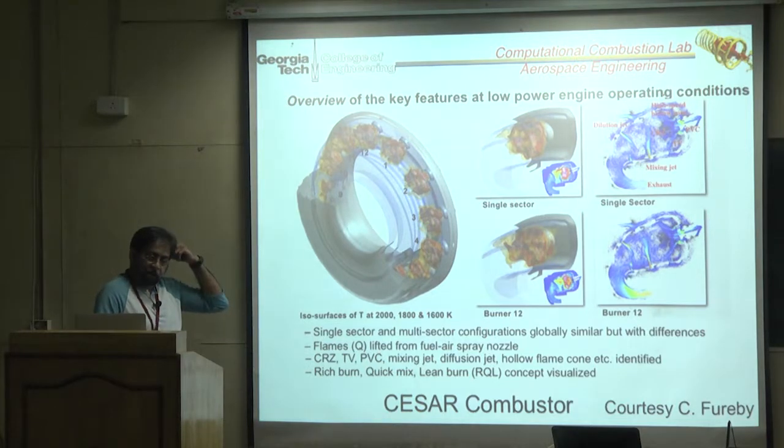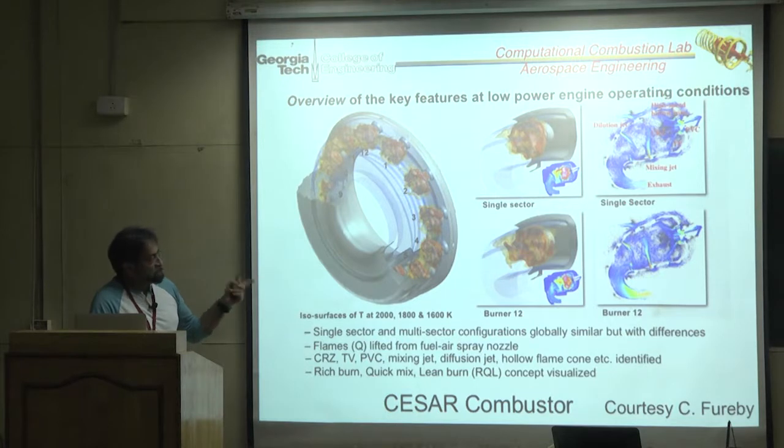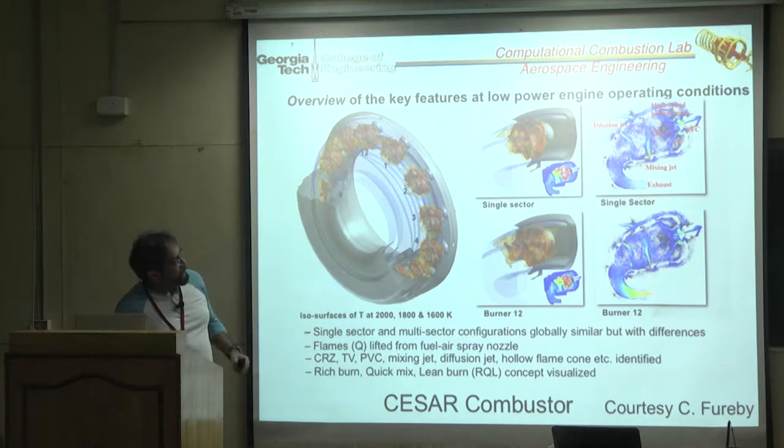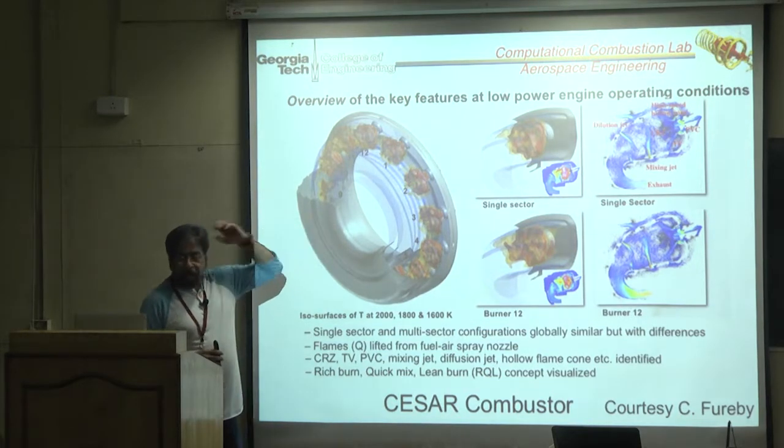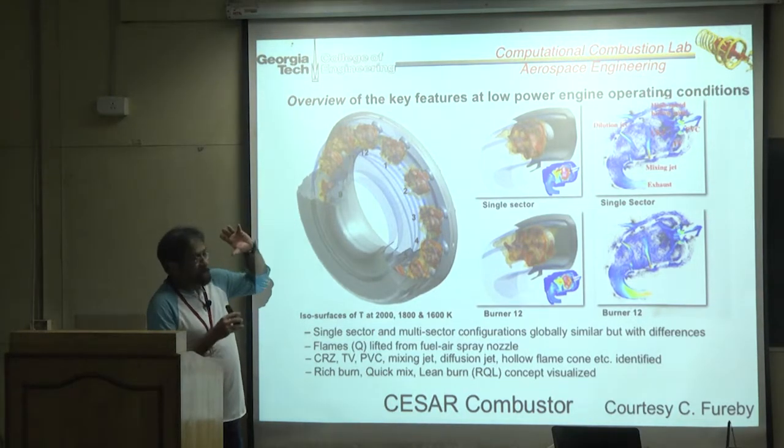The one I showed you was the longitudinal instability. But for typical burners, multi-burners, nobody's interested in that. Longitudinal instabilities rarely exist. It's the transverse instability that's very fundamental to these problems. Multi-burners are always, that's why many of the old combustors and gas turbines, aircraft engines had